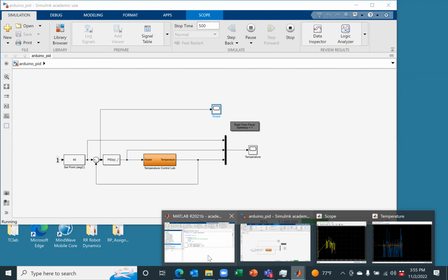So if you go to PID control using MATLAB, there is an excellent webinar on PID control using MATLAB, and they talk about all the different tools on how to do it. But at the end, when you perform the experiments, it's a matter of trial and error. Even though you run MATLAB, MATLAB is going to give you a result only as good as your model is. If your model is not accurate, the PID controls are not going to be accurate, and you will have to do some real life tuning. Any other questions?